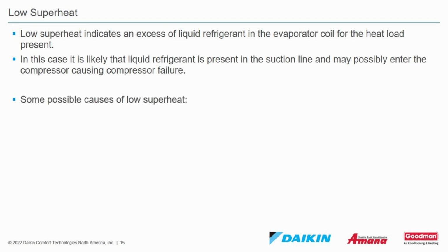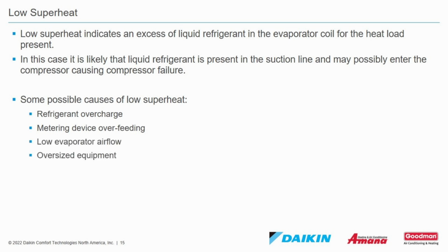Some possible causes of low superheat could be refrigerant overcharge. The metering device is overfeeding. Low evaporator airflow. Oversized equipment. Low condenser airflow or a dirty condenser. Low indoor heat load.